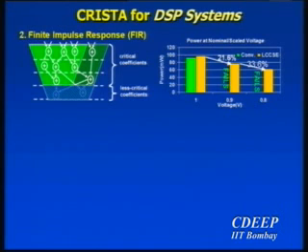But the interesting thing to note here is that the computation of these important coefficients is done using an adder tree, right? When you use an adder tree and a set of coefficients is important, you give a tree height for that. What it really means is that the critical path is not going to be more than a tree height of 4 or 5, let's say. For the other ones, you say I'm going to give them a little more; the constraint is not going to be 4, but 4 plus 1 or 4 plus 2, right? That allows more sharing, and you can reduce the area and power consumption that way.